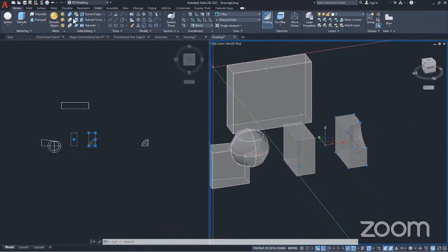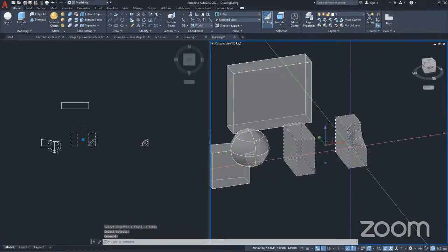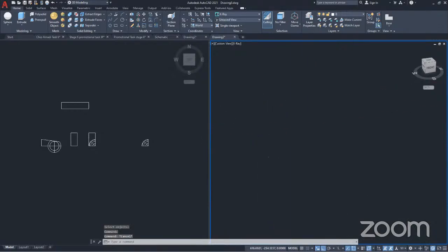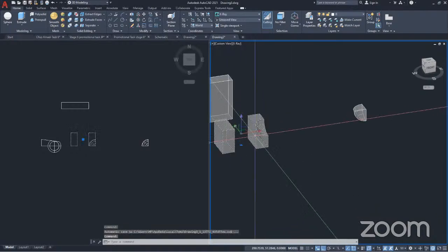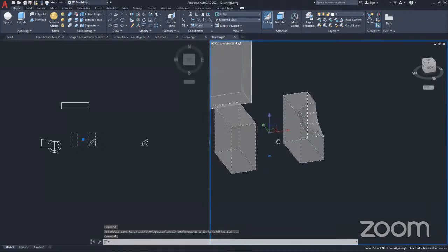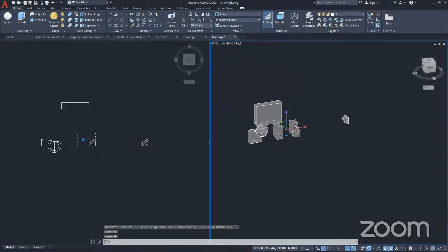Let's say these two were united like so. Let's do solid union. 1, 2, enter. Now you see both of them are together. And maybe you've done so many other things, like editing normal, you were modeling, and you came back, you want to use this as a single entity, but you notice these two are united, I've used the union command on these two, and I need to undo that. But you cannot use Ctrl Z because it will actually be disastrous. Your previous jobs done will be gone.